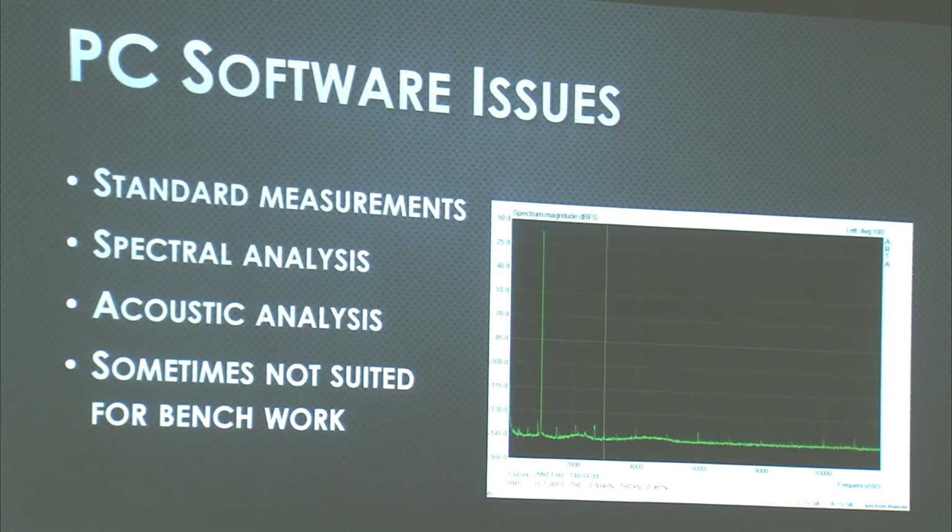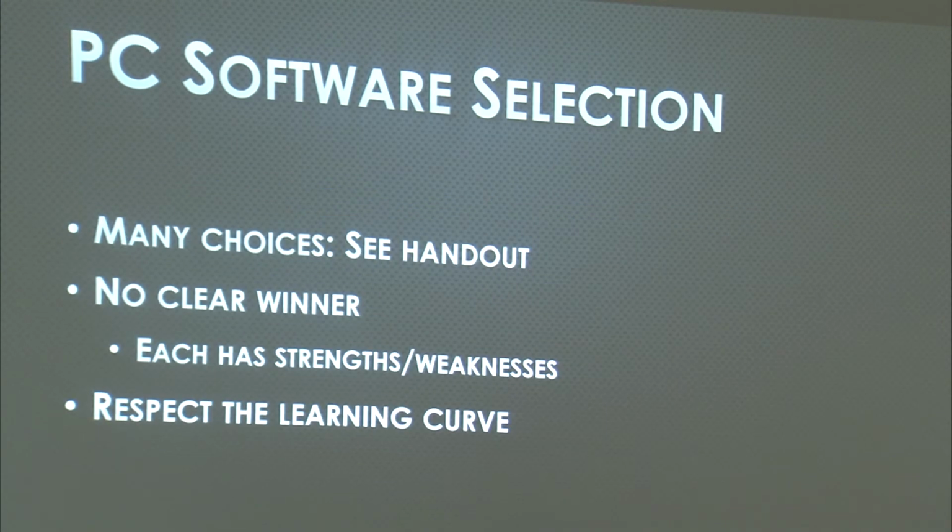Now, the other caution, and I mentioned it here, if you're using a sound card analyzer and you're trying to find the optimum setting for a bias on an amplifier, it can be pretty agonizing because to make that plot takes a finite period of time. So you'll turn the knob and wait, and turn the trimmer and wait. It's not real fast. With the analog analyzer, the one thing you have is you turn the knob and the meter moves. So it is a thing to be aware of in terms of what you're trying to do. You can do it with this, it's just not as easy.